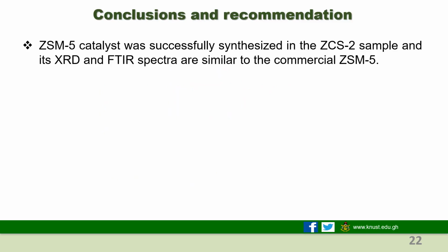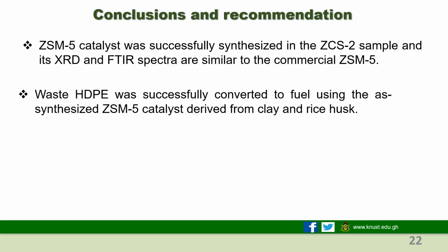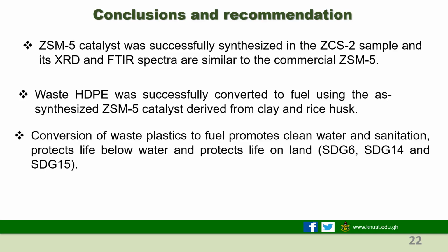In conclusion, ZSM5 catalyst was successfully synthesized in the ZCS2 sample, and its XRD and FTIR spectra are similar to the commercial zeolite. Waste high-density polyethylene was successfully converted to fuel using the synthesized ZSM5 catalyst derived from clay and rice husk. Conversion of waste plastics to fuel promotes clean water and sanitation, protects life below water, and protects life on land, helping us to achieve SDG 6, SDG 14, and SDG 15.